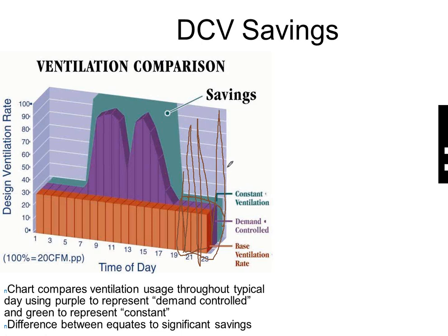I just did a presentation last week at IIT. We started off at 529 ppm in the classroom. We ended the class at 1,632, I think it was, 1,631 parts per million. It's all over the board. And it does make a difference whether it's in economizer mode or not. That kind of throws it off a little bit. But if you take the readings with a handheld CO2 meter in the dead of summer or dead of winter, then you'll get a good idea of whether the building's over or under ventilated. And I'll show you some stuff on that in a little bit.